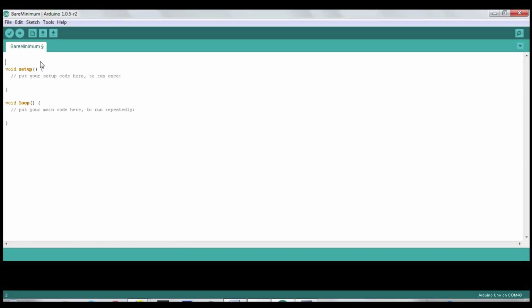Let us set our definitions at the top by using the integer operator int. We usually define the variables at the top away from the void loop function because we would like to only run this once to form the global variables, i.e. variables that don't change, unless you reassign it later on. Defining variables at the top also makes it more structured.